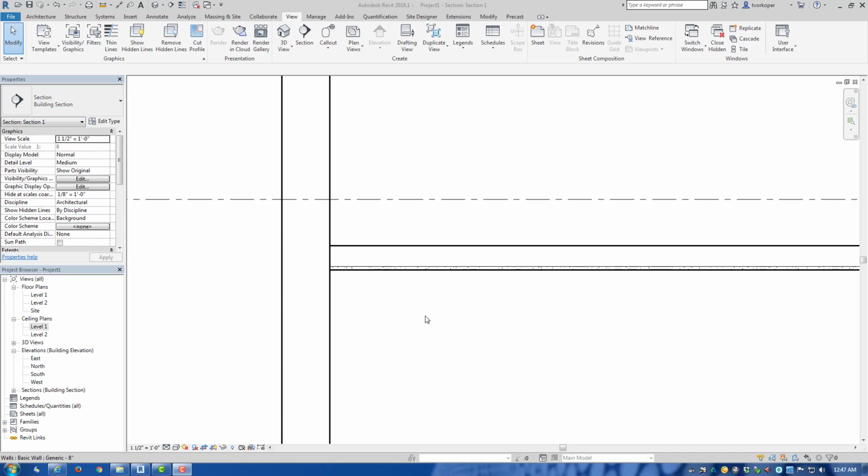In my experience, it is best to have the gypboard ceiling separate from the floor. So we should create a floor assembly that includes, say, carpet or tile over plywood over the joist. And then we should come in with just a gypboard ceiling and attach it to the floor assembly.